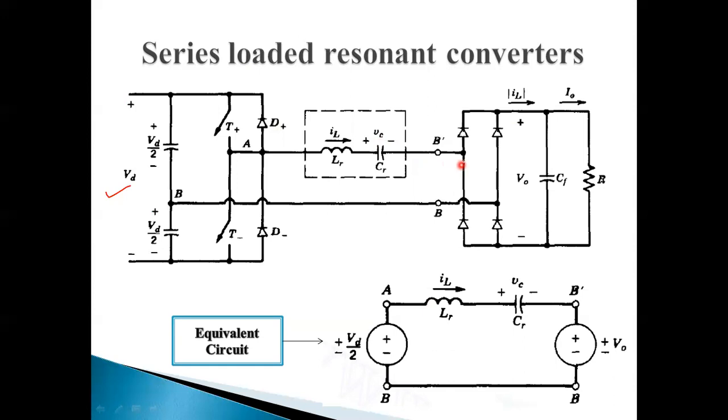After this are four diodes which convert the AC into DC, what is called a bridge circuit. After this is a capacitor again, but it is a filtering capacitor, because the voltage and current are oscillating.